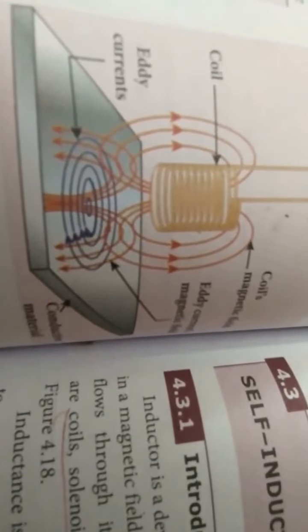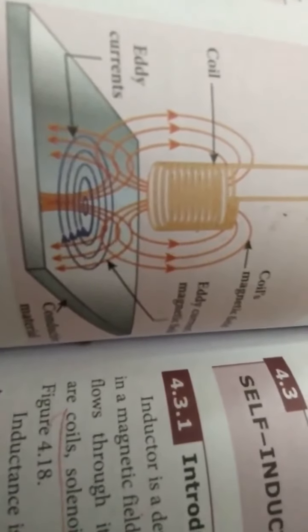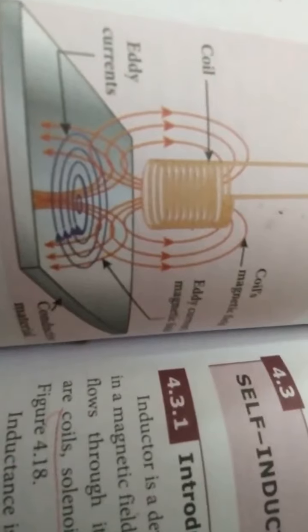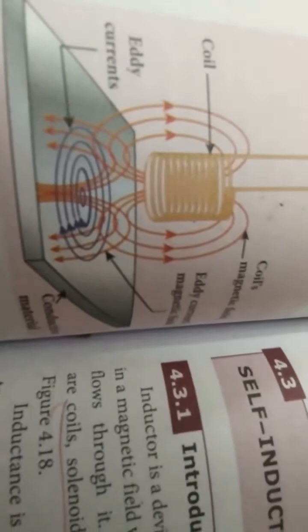If there is any change in the phase or amplitude of the eddy currents, then you can find that there are cracks or holes present in the system, and that can be rectified. The presence of defects causes changes in the phase and amplitude of the eddy current that can be detected by other means. So these defects can be identified with the help of eddy current testing.